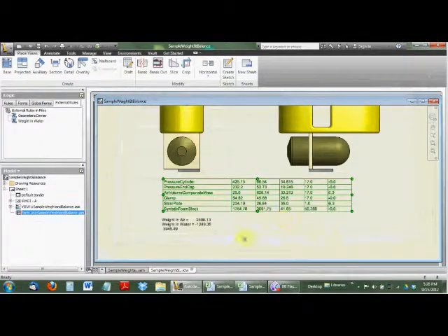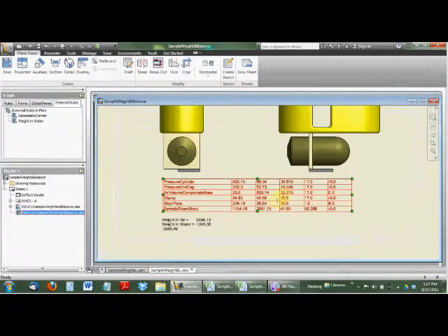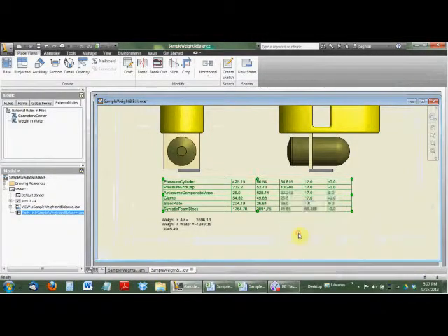So going back to the bill of materials, you can export this. I don't export it here because there's a lot of extra information I don't want to go into my spreadsheet. It just makes life more complicated. You export it from the parts list proper. So you make your parts list, edit parts list.